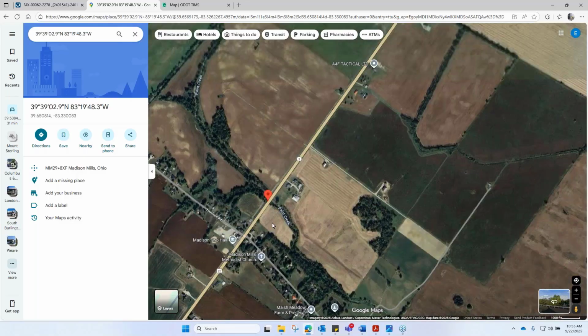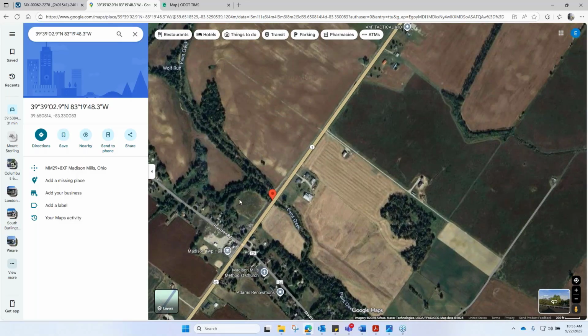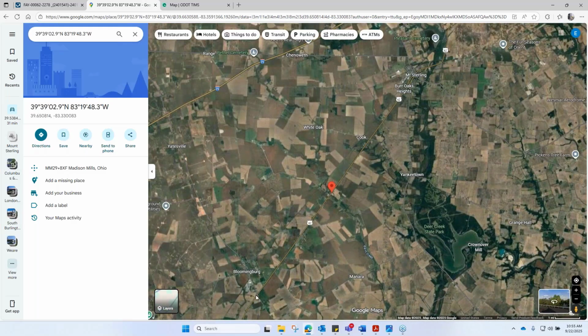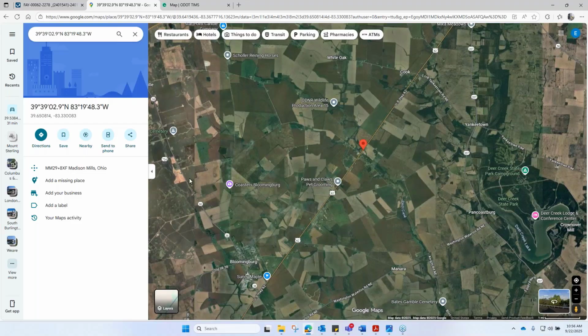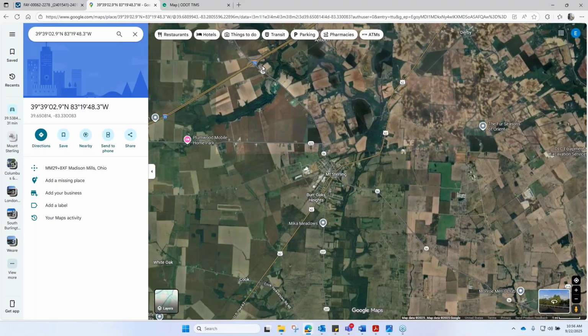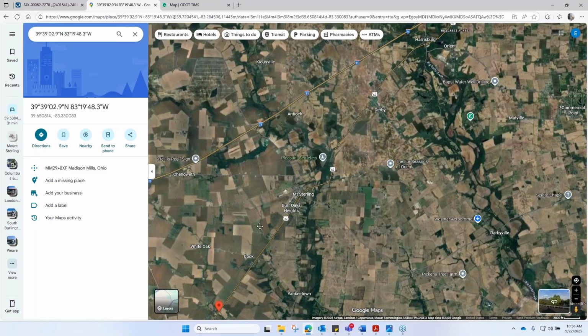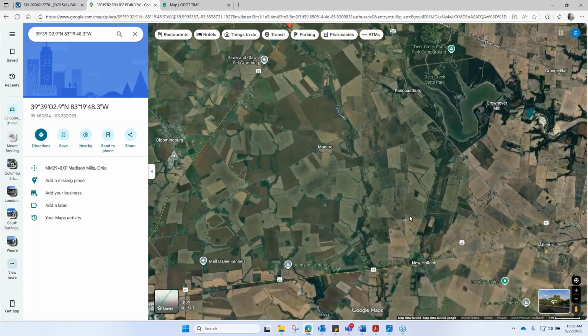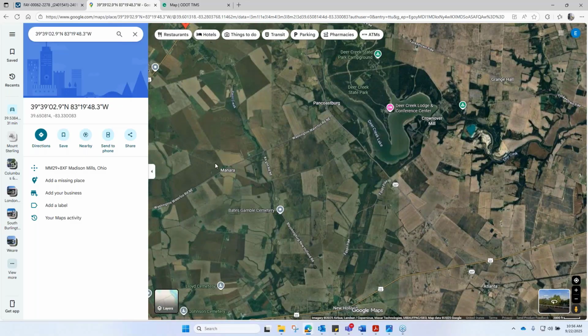Now, one tricky part though is that we can only detour interstate, US, or state routes onto other interstate, US, or state routes. So this one becomes a little bit more complicated. If I zoom out, it looks like I have maybe 2 options here, right? I can send them down 38 to 71, and they can swing back down, or I can kick them out on US 22 and have them cut back in on State Route 207.